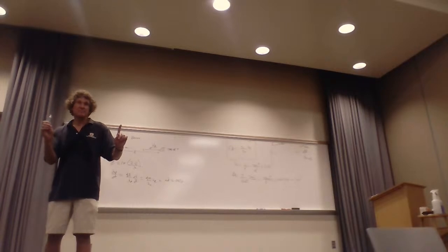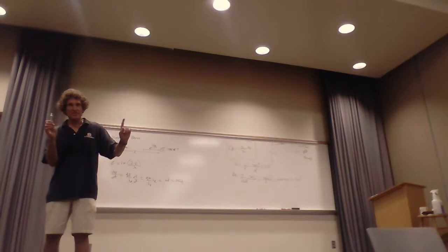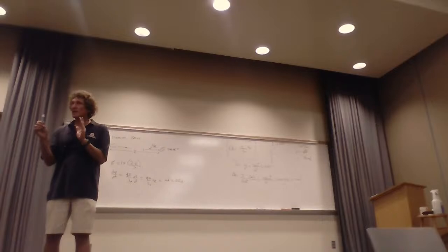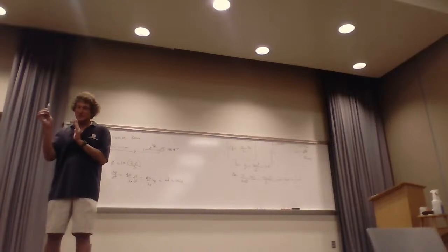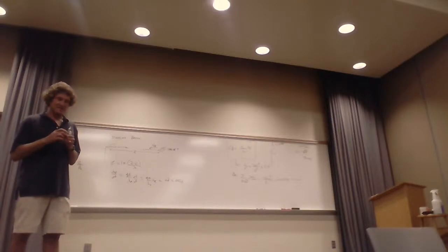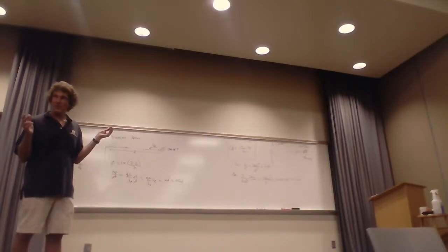Then they wait a short length of time. They take another snapshot of what's coming back. They digitize it, put it in there. Then they do convolution. You know what convolution is, or correlation, either one. And they see the time delay between what they sent and what is received. And that time delay is what they use to gauge distance. Now, the speed for Doppler shifting is another thing, but it does use coherency. And I'll get into this if I have more time. I'm going to show you a little bit more about radar, but y'all follow me on Doppler?